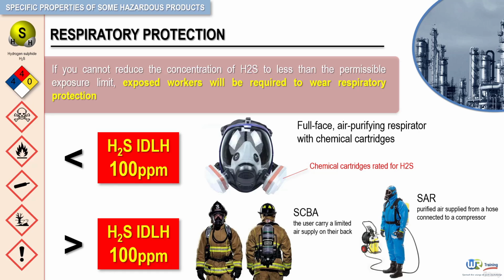If you may be required to wear a respirator or breathing apparatus, then you must undergo a medical evaluation by a licensed physician who will determine your ability to wear a respirator effectively. Annual fit testing is also required to ensure that you can achieve a proper fit in the type of respirator you may be asked to wear. If you may be required to wear a respirator, you will receive specific training on the types of respirators used at your facility, their locations, and the specific situations which require their use.